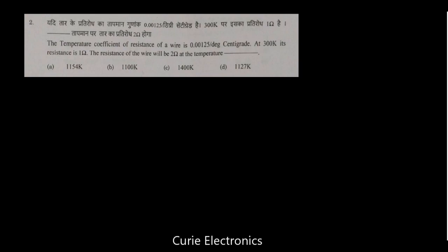To solve this question, we should know one equation, that is RT. I will write it at the top right. RT equals R reference multiplied by 1 plus alpha, that is the coefficient of temperature, multiplied by the difference between the temperature at which we have to find and the reference temperature. This equation you should know to solve this question.